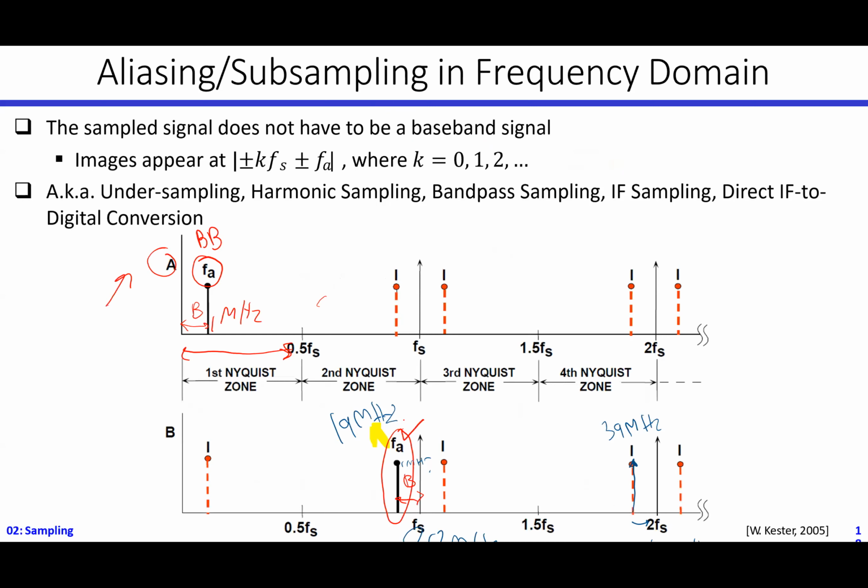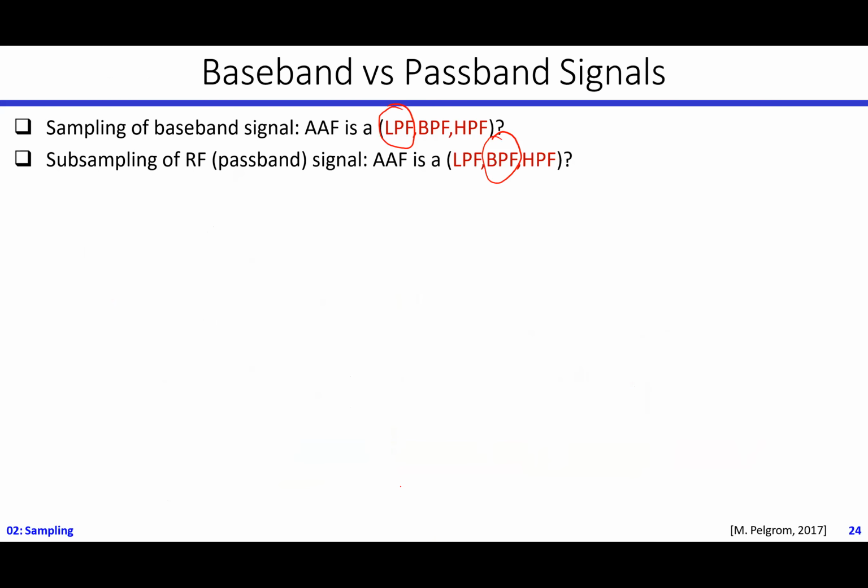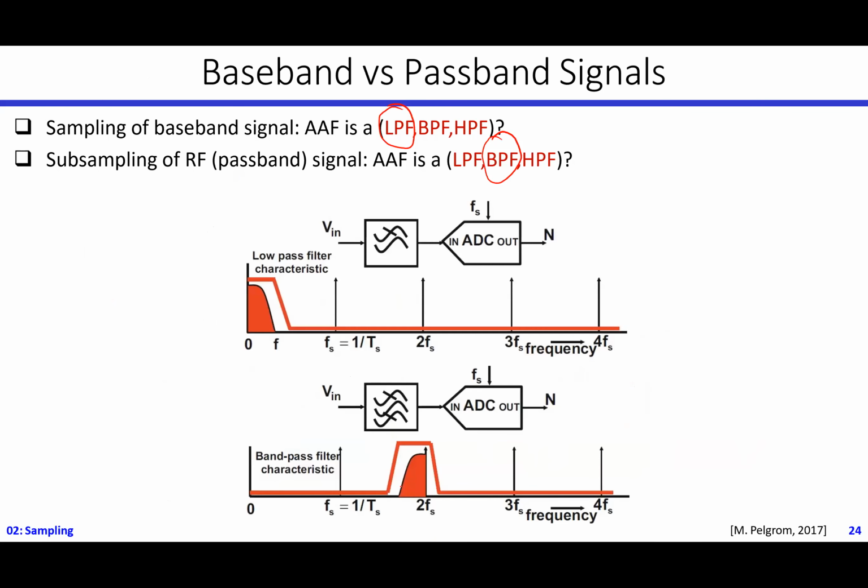And that's basically coming back to the point here. If this was my original signal, and before I subsample it, if there was anything here in the baseband, for me, it's just considered as noise at this moment. So before I subsample, I will use a band pass filter here to just take this original signal and then subsample it. So when it comes into the baseband, it will be clean, it will not mix with anybody else. Okay, so this was what we just said.